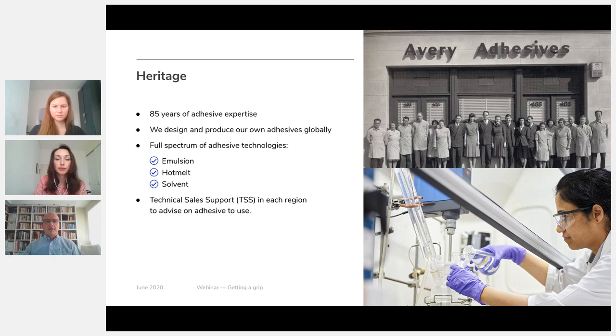No, absolutely. On one of these pages, you actually find a very good overview of the 6 key adhesives that we have for the automotive industry, and you can find back the criteria that I've used as well. So the surface energy is obviously very critical, as well as the roughness, and thirdly the durability of these labels. So you will find very elaborate information on these adhesives on our website. Yeah. Thank you, Renee.